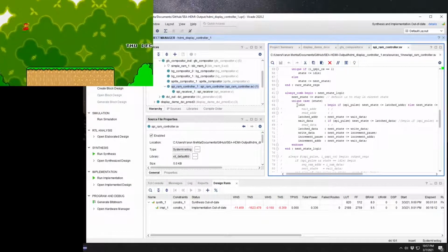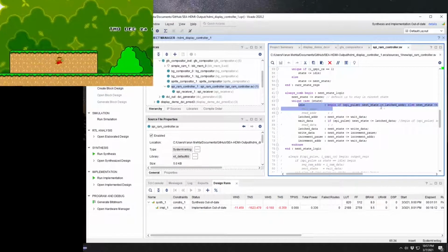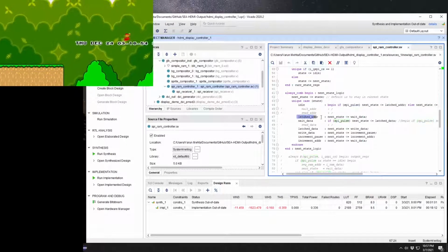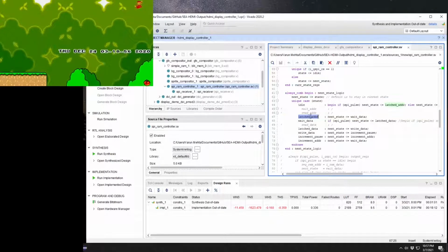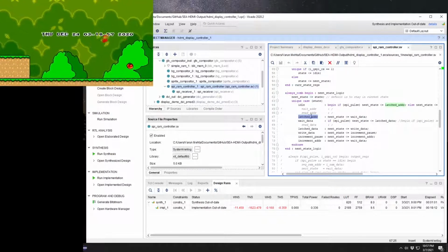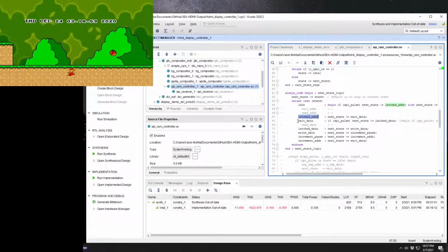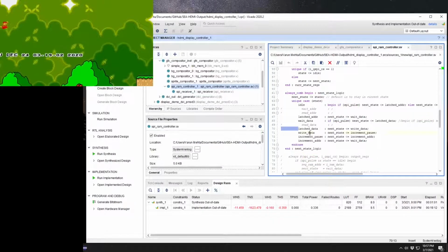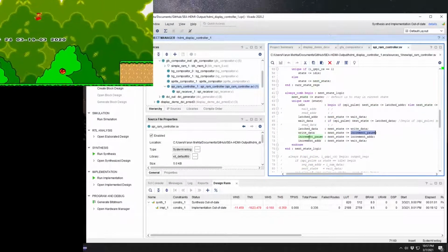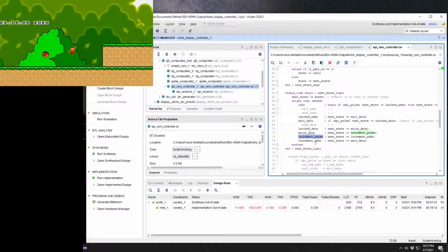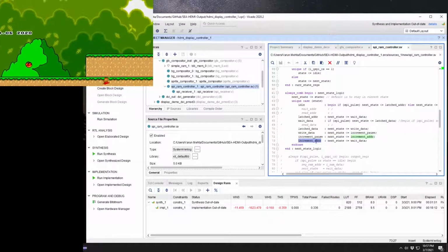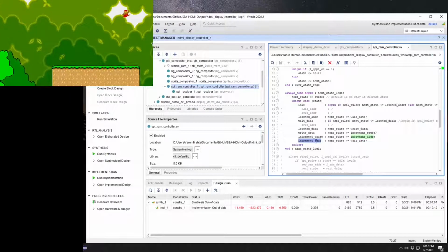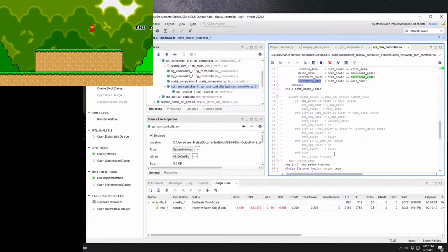But basically, the idea is anytime a new transaction begins, we first receive the address that the memory write should begin at, and then with every additional 16-bit word that we receive, we will write data to that address. And once we've written data to that address, we will increment the address so that the next word of data writes to the following address in memory.